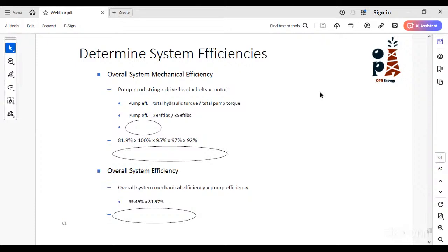So what is the working temperature for your application? Of course, it will be 250, not 300. So you should choose or design correctly the best elastomer and bonding material for the temperatures that you have.